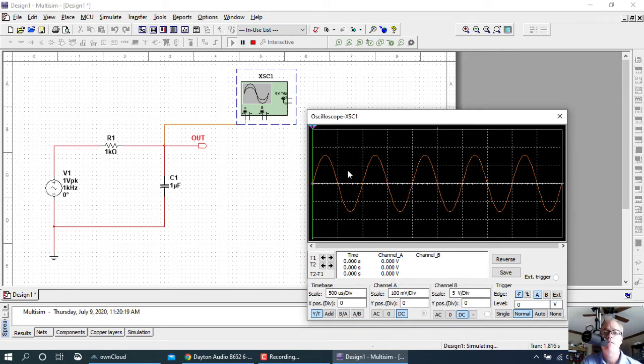And remember now, an oscilloscope shows two parameters of a signal. It only shows two. It shows voltage, which is in the vertical axis, or the vertical dimension is going to be voltage. So we're looking at voltage that's increasing and decreasing. And then on the horizontal axis, what are we measuring there? We're measuring time. So from left to right is time. So don't take that for granted, because we're about to show a different instrument that will give us a different display of the same signal.